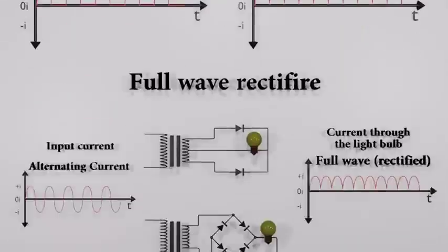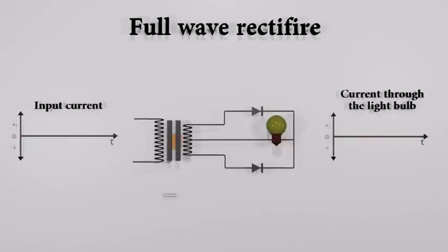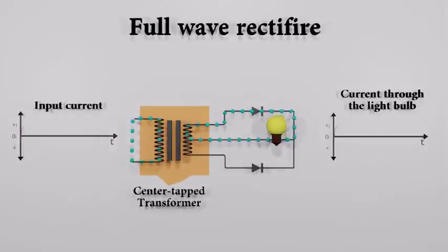There are two major types of full-wave rectifier designs used frequently. The simpler design uses 2 diodes. If the transformer is center tapped, then 2 diodes back-to-back can form a full-wave rectifier. It converts both the positive and negative halves of the input waveform to a single polarity, positive or negative, at its output. By using both halves of the AC waveform, full-wave rectification is more efficient than half-wave.